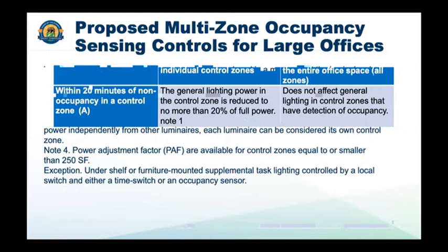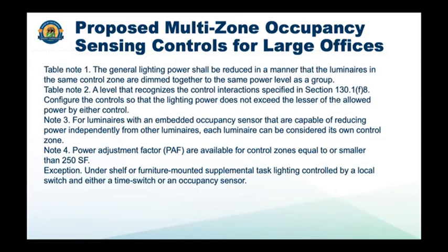And the last note, Note 4, is more or less a pointer note telling that PAF, power adjustment factor, is available for control zones smaller than 250 square feet.